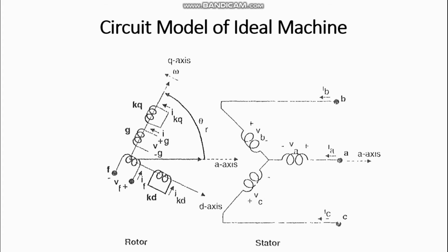As we know, in a squirrel cage induction motor the no load slip is very, very small, so it helps our synchronous machine rotor reach a value very close to its synchronous speed. Then you energize, connect this Vf with your rotor winding, and it produces a magnetic field, and then the rotor accelerates itself and locks by means of magnetic interlock.